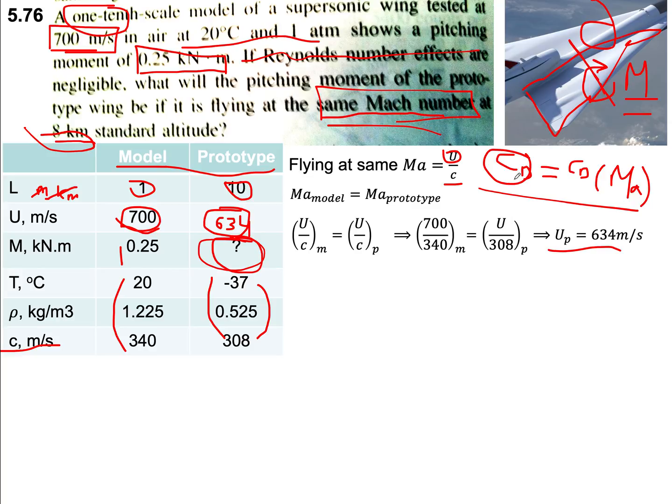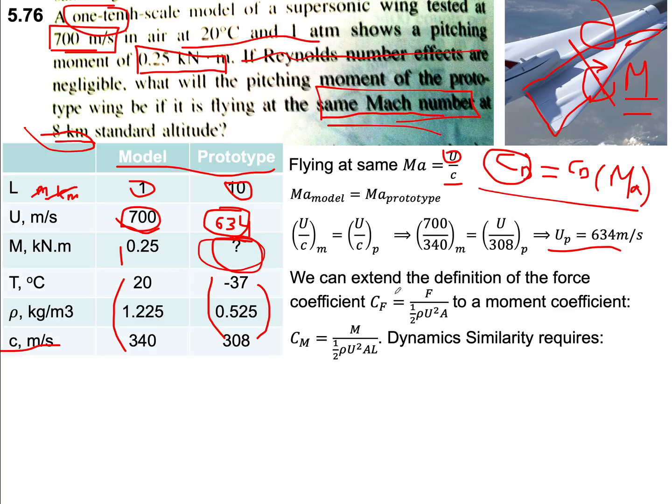And we know what the definition of the drag coefficient is. It's a force coefficient. We have the drag coefficient, the lift coefficient, and whatever other force coefficient you would like to have. Now if I multiply that force by a distance L, that would be a moment coefficient. So by knowing the force coefficient, we can expand it to give us a dimensionless moment coefficient, which is just the moment divided by half ρ V squared, and you'll see the extra little term, the L, just to get the units scaling.